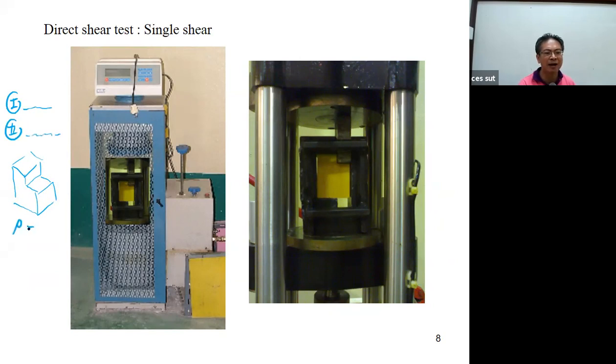Then you find the density by dividing the weight by the volume. Most of the time, a specimen with higher density is supposed to have higher strength, because higher density wood has more grain and can take more loading.